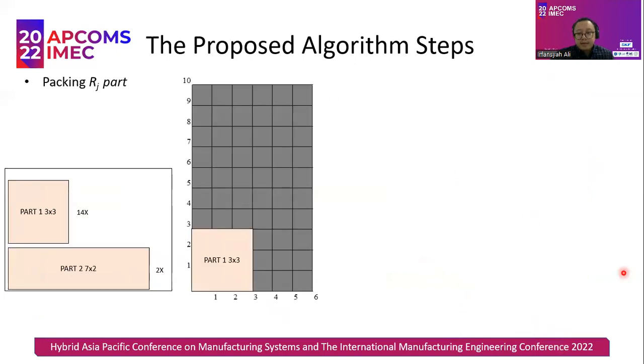Then after that, the type 1 part, which became the previous RJ, is packed on the next sheet. Sheet selection is done with condition 2, when the priority part doesn't exist anymore and the amount of material is greater than 20%. Then a large sheet is used. The following step is an example of how the best fit heuristic algorithm from Chen et al. 2019 is done. Picking a type 1 part will form the initial layout and generate an angle occupying placement, or AOP,